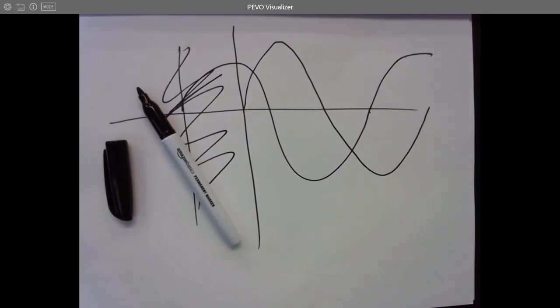It just has a little potentiometer, so you can change the resistance of the circuit. So you're changing the amplitudes easily, and you are generating a third signal with a different phase or different amplitude easily, just by tuning the amplitude. You don't even need to tune the phase of the input, but the phase of the output will be changed by changing the amplitude. Why is that?